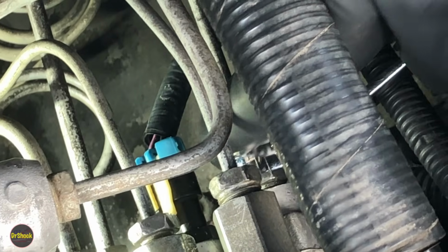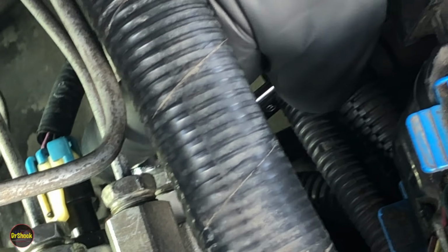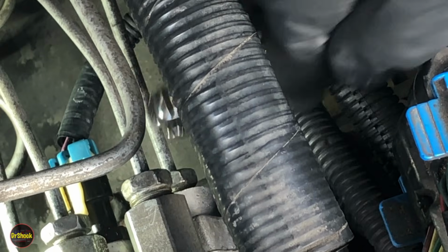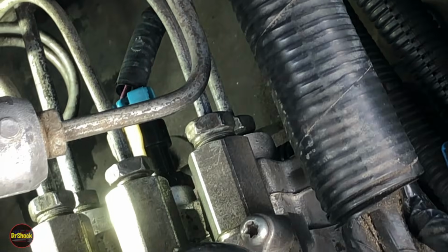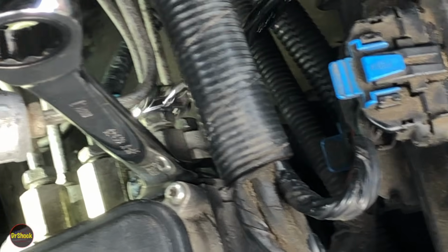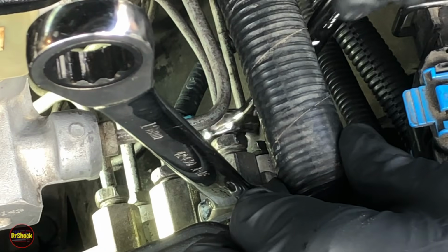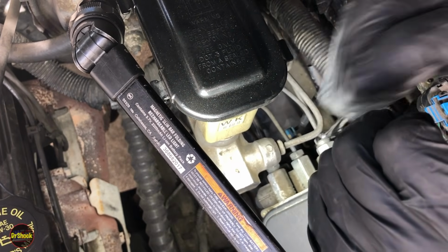Want to get it on evenly, of course. And what you'll be able to do is get it on by going down in between these two. Now it's really awkward, but all you need to do this for is the initial breaking of the torque. Similarly, when you go to do this one up here on the top, you'll want to have your 19 in position for that one. Again, you're going to come in here from this side. You might have to work this harness out of the way. We're going to come in here and break the torque on each of these.